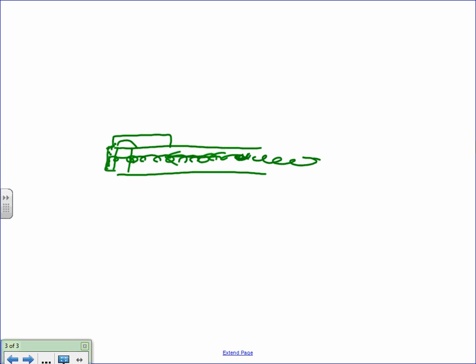And what it's supposed to do then is not only send an alarm to the fire alarm system that says there's smoke, it shuts that air handling unit down. So there are relays programmed into the starter of that air handling unit that completely shut it down.